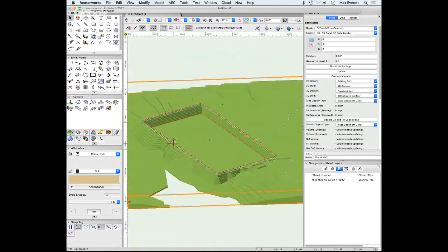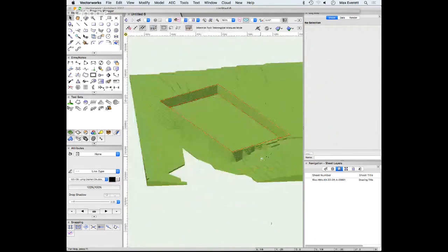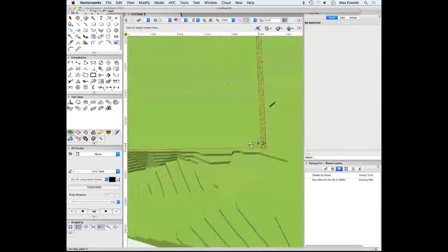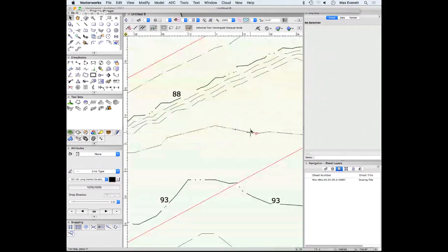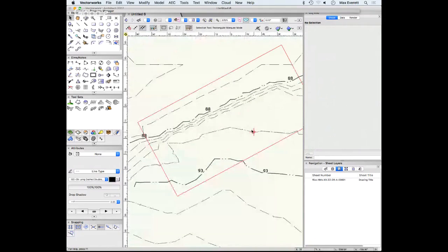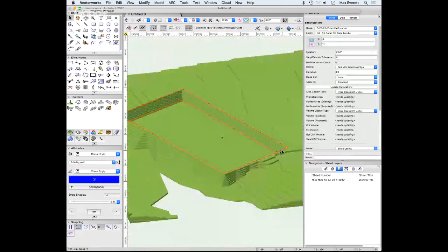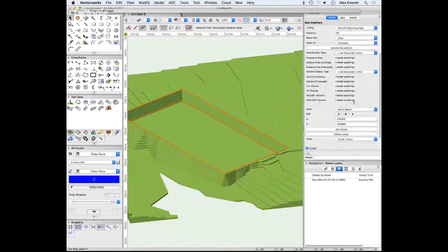But it might also be because the top rectangle is higher. I mean, we could drop that down again and play with it. But you're going to get anomalies where the ramping up to the edge of the first modifier doesn't always work. And yeah, you're right. It does ramp ever so slightly, doesn't it? But on plan view, it doesn't show that. But when you created the second one, it seemed like it's smaller than the first one. Yes, it did seem like it. So when you drop it down, that's how it could be. It could be to do with slope definition.